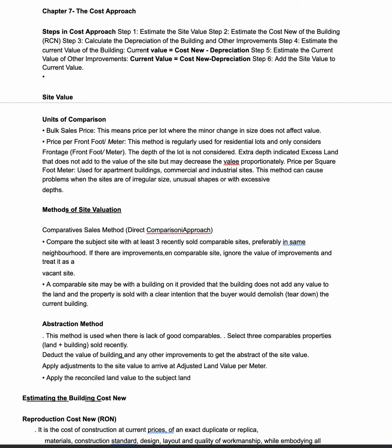The first step is to estimate the land or the site value. Then estimate the cost of the building, including any attached or built-in structures. Estimate the depreciation of the building, how much value of the building is lost due to its age, functionality, or location, and estimate the current value of the building, which is the cost of a new building minus the depreciation, and then estimate